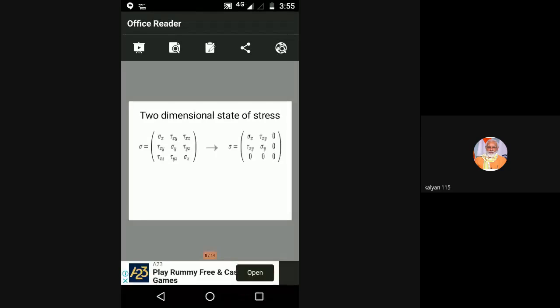But one thing to remember: normal stress means the stress induced perpendicular to the direction of the plane is called normal. Ultimately, the normal stress is further classified into 2 types: one is the tensile stress and the second is the compressive stress. The stress that is away from the member is called tensile. Towards the member, it is called compressive.